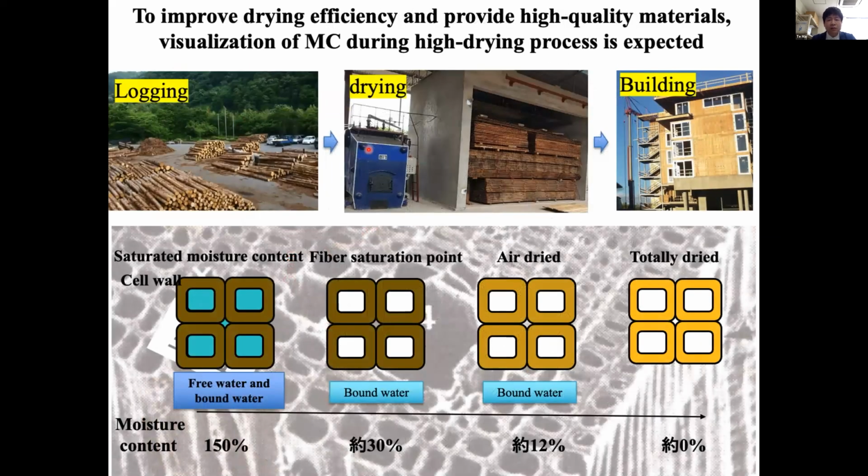In order to earn a stable mechanical property, an extremely important process is drying the felled wood. Otherwise, the built house will deform or even collapse. The traditional method is just to put the felled wood outdoors and wait for it to dry before using it. However, because such a natural air drying method is time-consuming, nowadays it's difficult to rely on it alone to meet the demand for mass production in the wood industry. In fact, almost half of the felled wood here is dried by artificial heating systems.